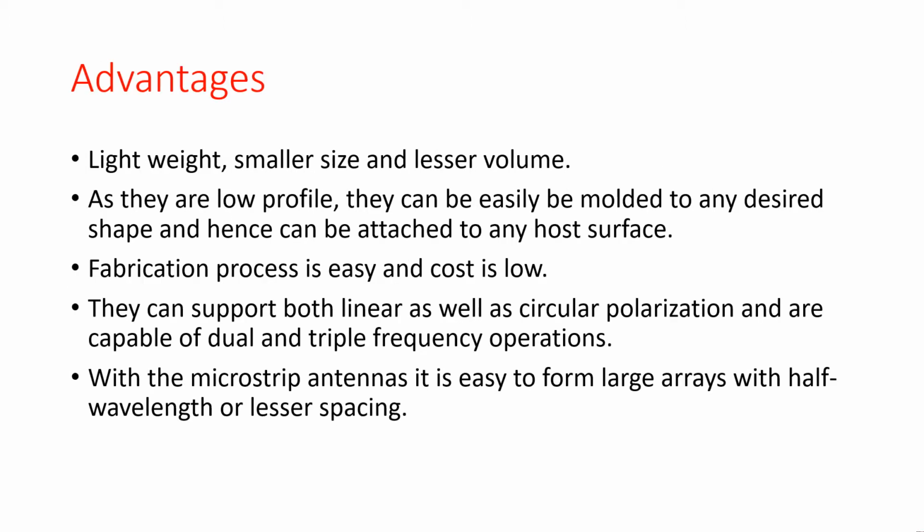Now what are the advantages of microstrip antennas? Usually the main advantage is that it is lightweight, small in size, and of lesser volume. You can see from the size itself it is of very little weight. They are very low profile, can be molded to any desired shape, and can be attached to any host surface.